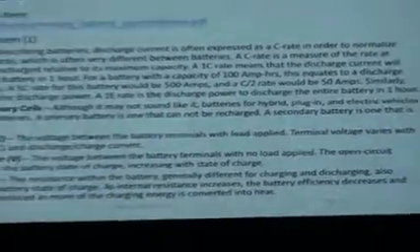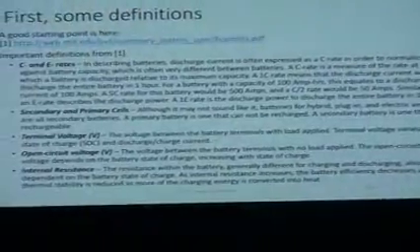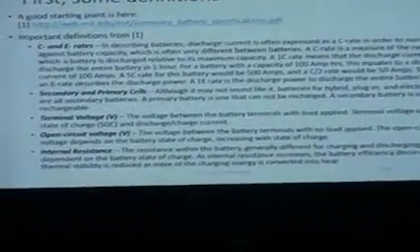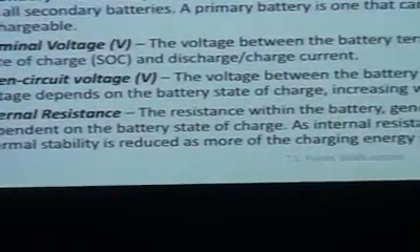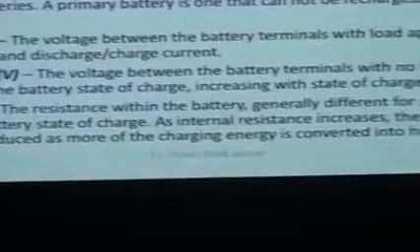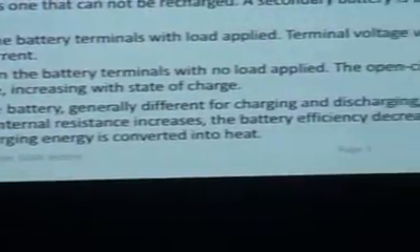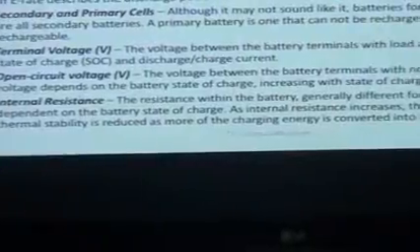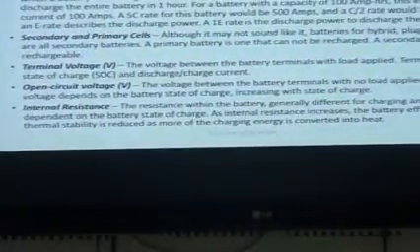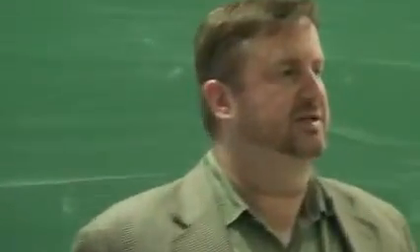The internal resistance, we'll talk in the coming days a little bit more about that. The internal resistance is the resistance that's inside of the battery. It's part of the electrolyte, it's part of the electrodes, and as you might expect, the higher the internal resistance, the less efficient the battery will be, because resistance, when current flows through it, creates heat. And so that's non-useful energy.